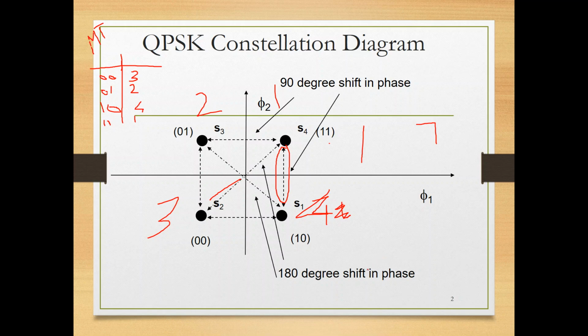Also, it causes intermodulation products. Intermodulation products are kind of adjacent channel interference. So your signal spreads. When it spreads, it causes interference to adjacent symbols, and this is what we call intersymbol interference. So we don't like this.